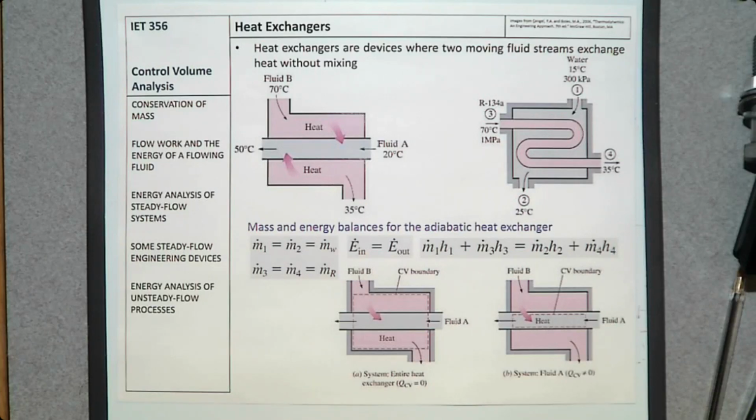So if you want to maximize the rate of heat transfer, you need to maximize the surface area between two fluids. That's why if you look at the fins in your car engine, you see many panels aligned together, trying to increase the surface area.